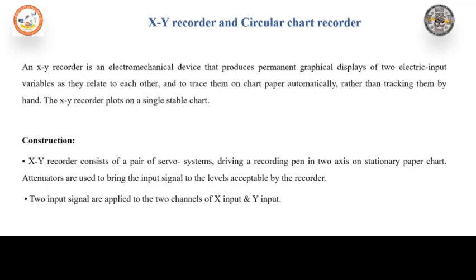So, what are the advantages of XY recorders? They are rather economical to operate, as ordinary low-cost paper can be used for the chart, and they are easy and convenient to use. The disadvantages of XY recorders are that in comparison to strip chart recorders, they are more expensive to buy and cannot be employed for continuous recording because of the electromechanical mechanism used for the movement of the pen. The frequency response and speeds of XY recorders are inherently limited.